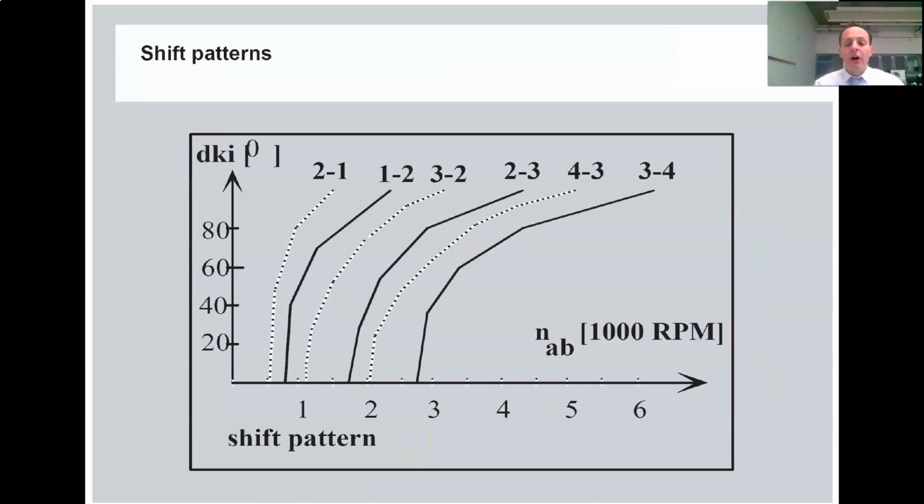So depending, for example, in this case, on the slope of your road, you have different curves here, which are represented as a reference value of the speed of your engine, and depending on the shift, you have a different curve here, and depending on this curve, you have also the changing of the gear, which is decided on the basis, for example, here of the slope of your road and the speed of the vehicle.